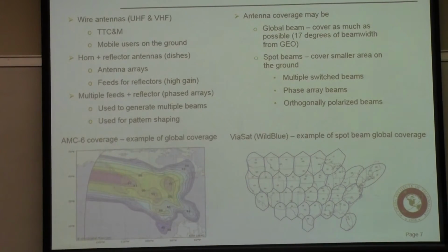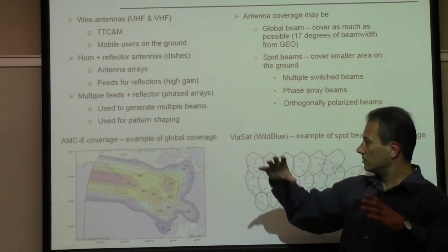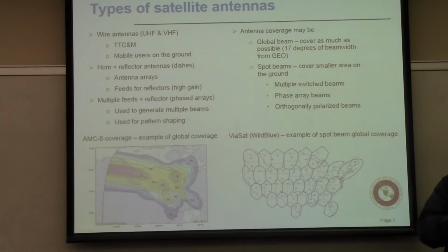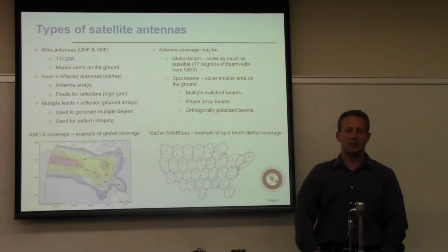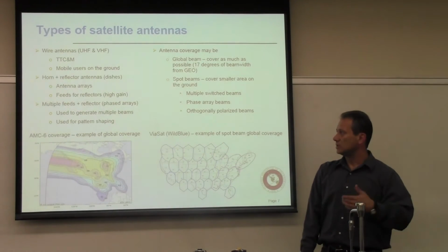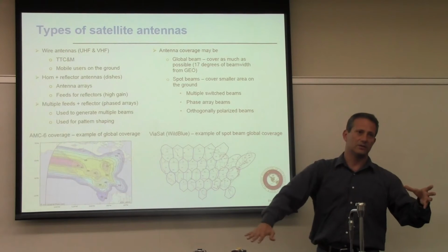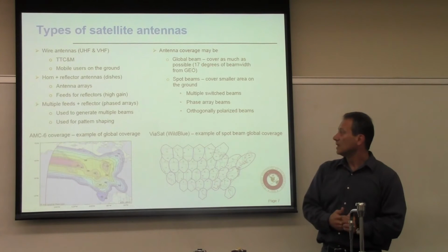And then for the communication systems, you use horn antennas, called that because of how they look. You have a feed and then you have a horn that can be either rectangular or spherical. And then you use dish antennas that might be fed with a horn, but then you have this reflecting surface behind that allows you to shape your beam.